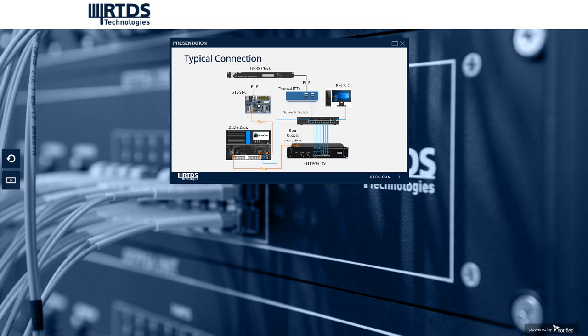Here is the typical connection of GTFPGA-SV. On the left, this is the RTDS simulator. You simulate your power system all in the simulator here. So the voltage and the current out of the secondary of CT and PT are sent to the GTFPGA hardware. Within GTFPGA-SV, the voltage and the current will be packed as SV packets and sent out to the Ethernet. And the external IED will be able to subscribe to the SV stream and retrieve the voltage and the current, and then go through their protection algorithms.